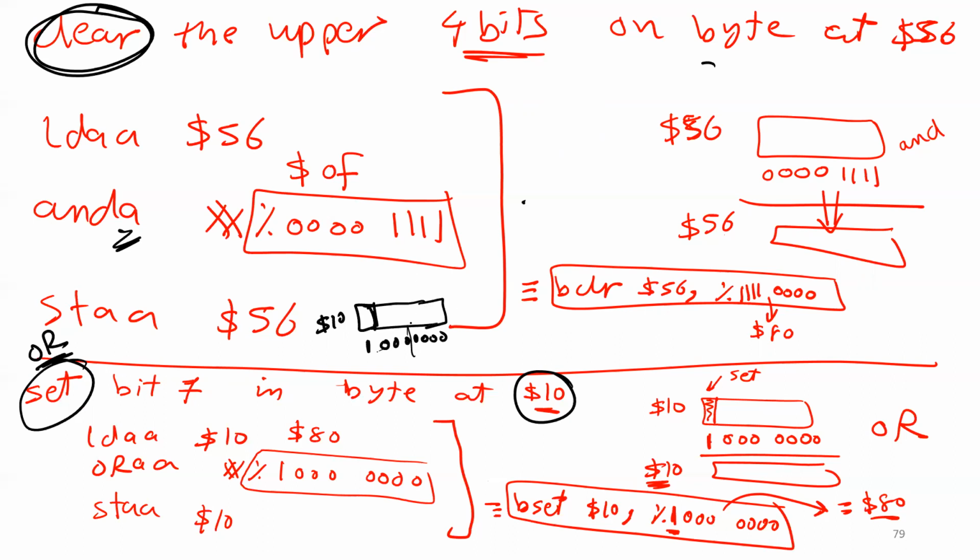Okay, guys. So here, that's what I have to do. I have to do an OR operation, okay? And the bits I want to set, I have to put 1. The bits I don't want to change, I put zeros, okay?